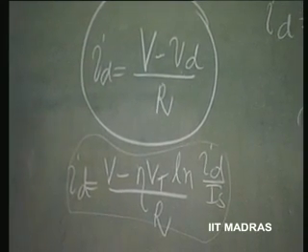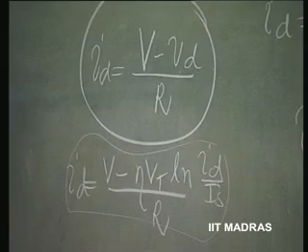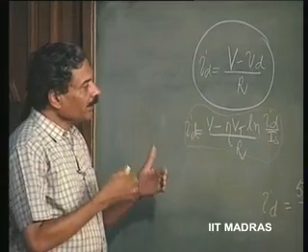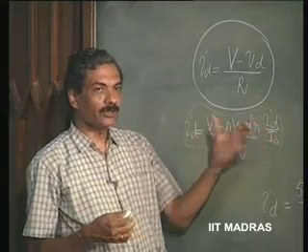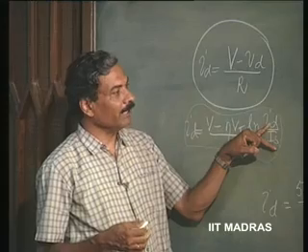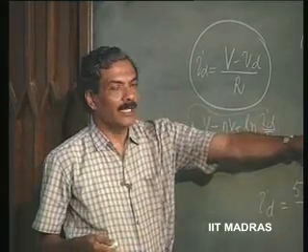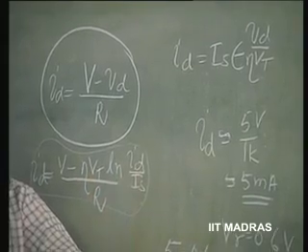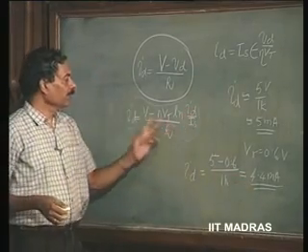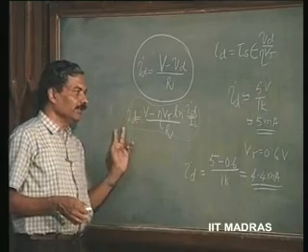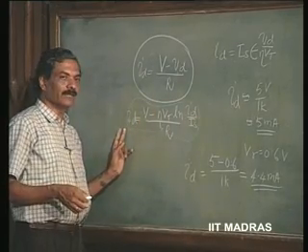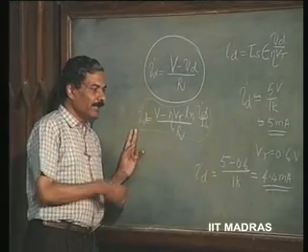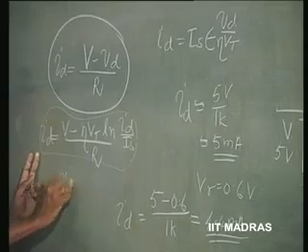So, how do we really get the exact solution for this? This can be done by what is called repeated usage of the equation, that is how a computer also solves these nonlinear equations. First we put the value of I_D as 5 milliamperes, that is this approximation, or this better approximation, 4.4 milliamperes here, and evaluate I_D. Then use this I_D here and again evaluate it. So, in successive steps we will be approaching the actual value of I_D.